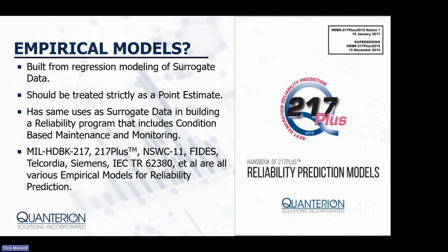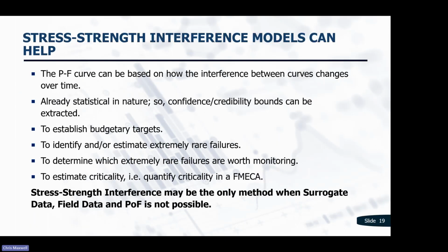Empirical models, we do have an empirical model ourselves generated for electric parts, electronic parts, or EEE type parts. There's also the classic Mil Handbook 217, NSWC, Naval Surface Warfare Center for mechanical parts, FIDES, Telcordia. There are many different empirical models that can generate point estimates similar in utility to surrogate data.